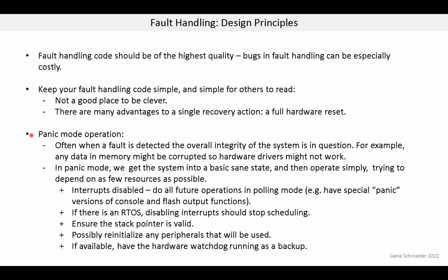So now panic mode operation. Often when a fault is detected, the overall integrity of the system is in question. For example, any data in memory might be corrupted, so hardware drivers might not work. In panic mode, we try to get the system into a basic sane state and then operate simply, trying to depend on as few resources as possible.